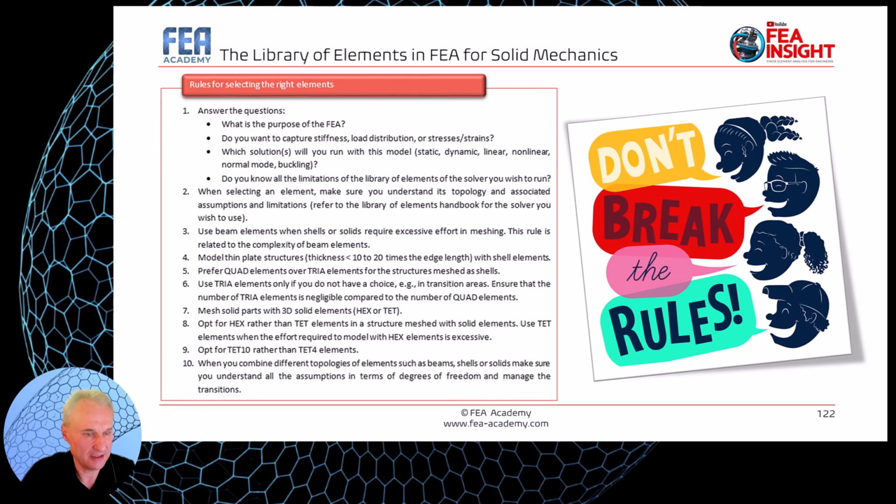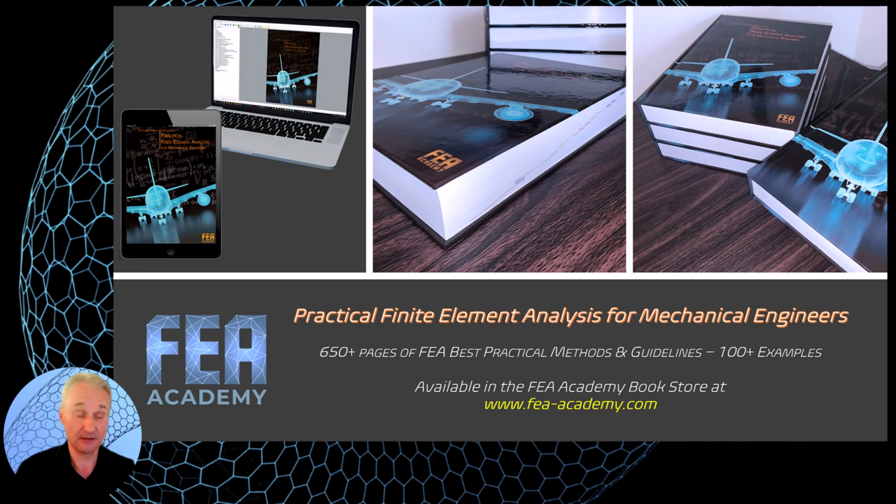When you combine different topologies of elements, such as beams, shells, and solids, make sure that you understand all the assumptions in terms of degrees of freedom and manage the transitions, okay? Because it's very important. Keep in mind that all the elements do not have the same degrees of freedom. So maybe you will have to manage the transition between the degrees of freedom. So that's it for this presentation.